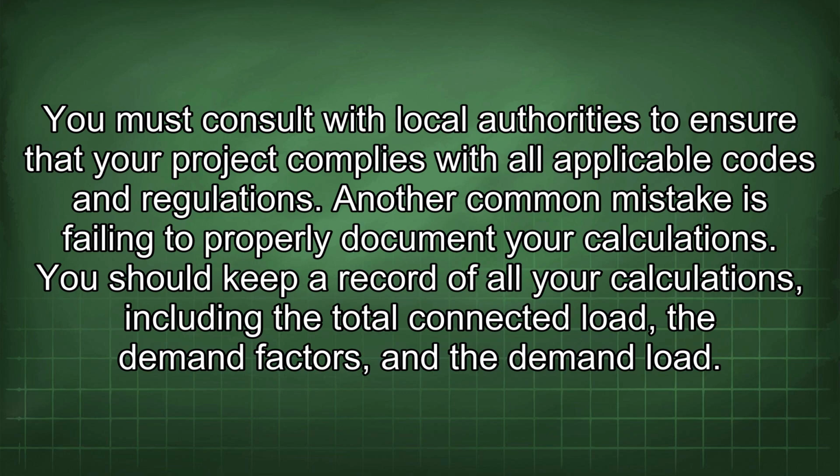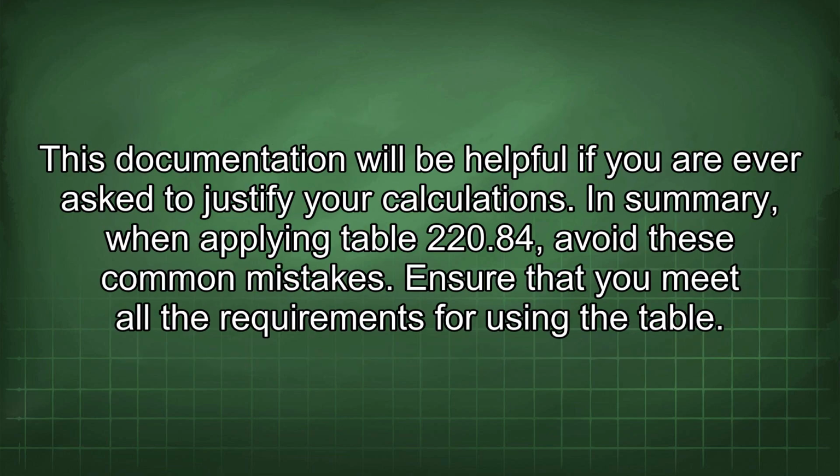Another common mistake is failing to properly document your calculations. You should keep a record of all your calculations, including the total connected load, the demand factors, and the demand load. This documentation will be helpful if you are ever asked to justify your calculations.